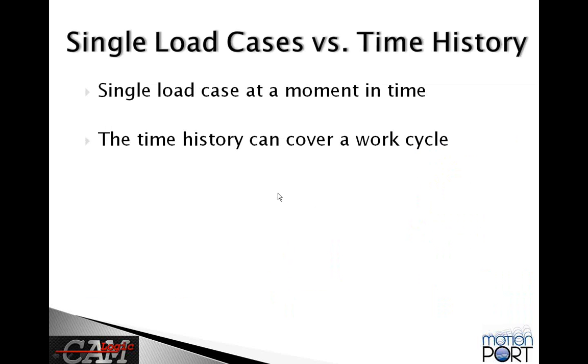Okay, another variation here on the different types of loads is you can have a single load case at a certain moment in time, or you can have a time history that might cover a work cycle. The reason to do an analysis with a time history of loads is that you may have a situation where the forces in the system actually have to do with things like the inertial forces, and kind of tracking changing conditions on the component.